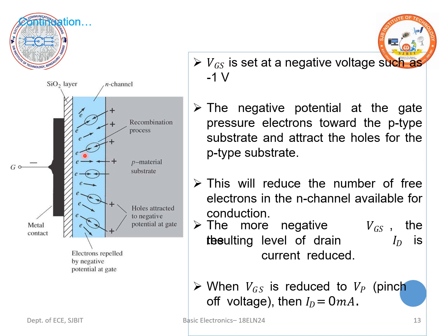As the number of electrons reaching the region increases, the n channel is formed gradually and the resistance between source and drain decreases. Thus, the resistance seen by the drain source supply VDS depends on the voltage applied to the gate VGS.